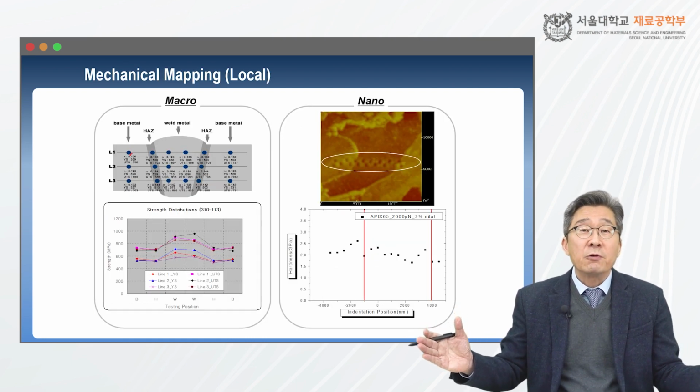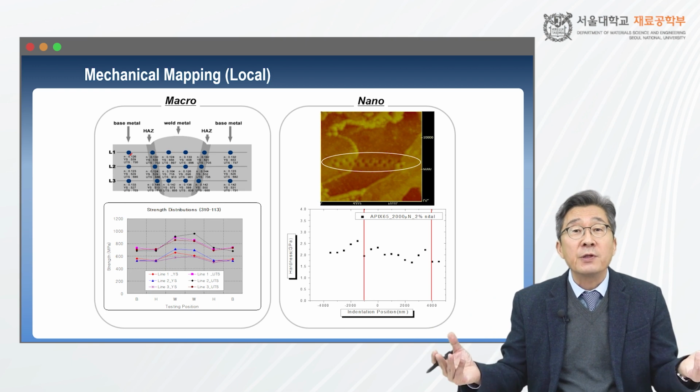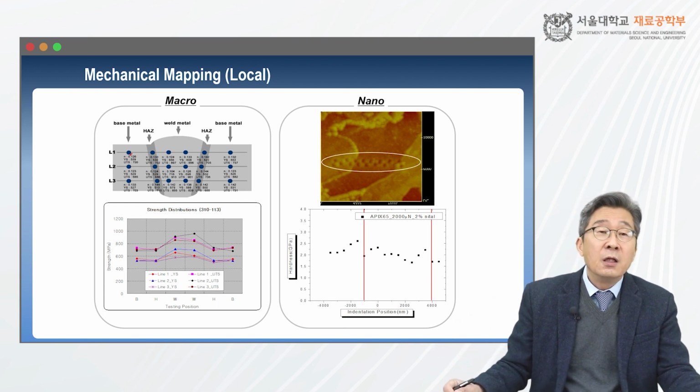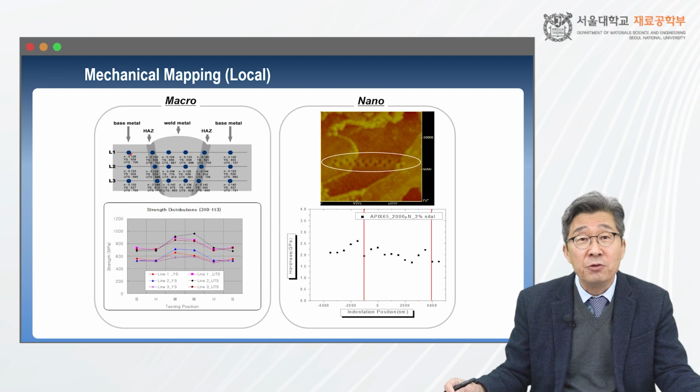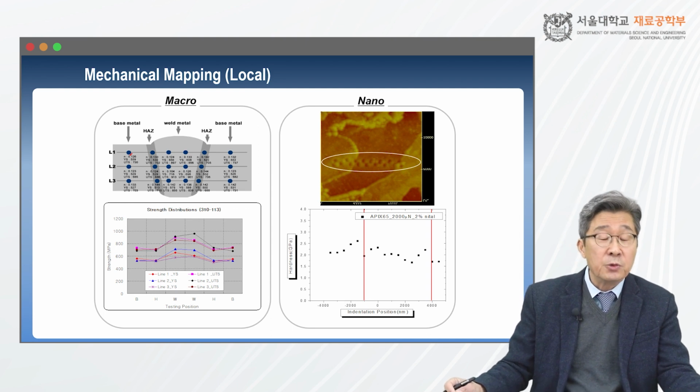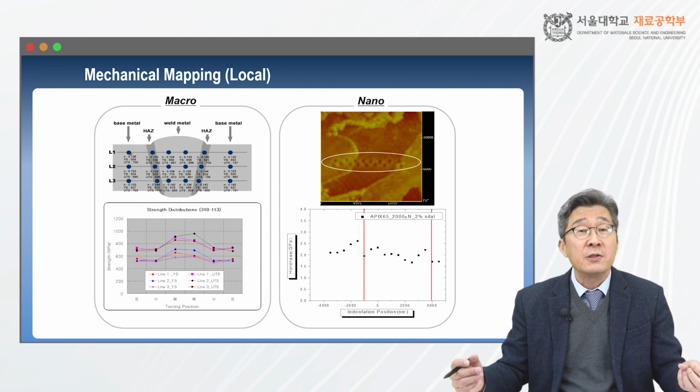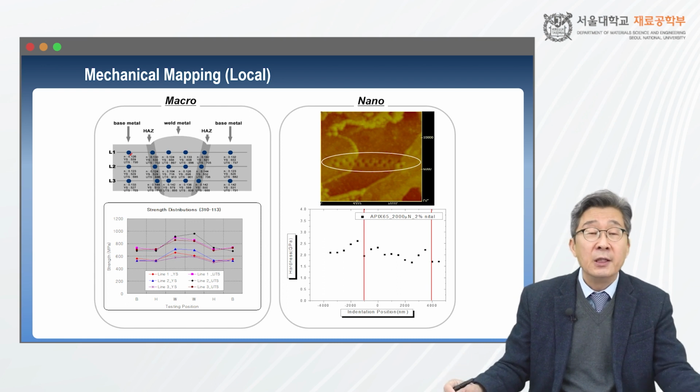What is the characteristic of instrumented indentation testing? Indentations no deeper than 100 micrometers are usually suggested to avoid surface damage, because we need in-field testing done non-destructively.